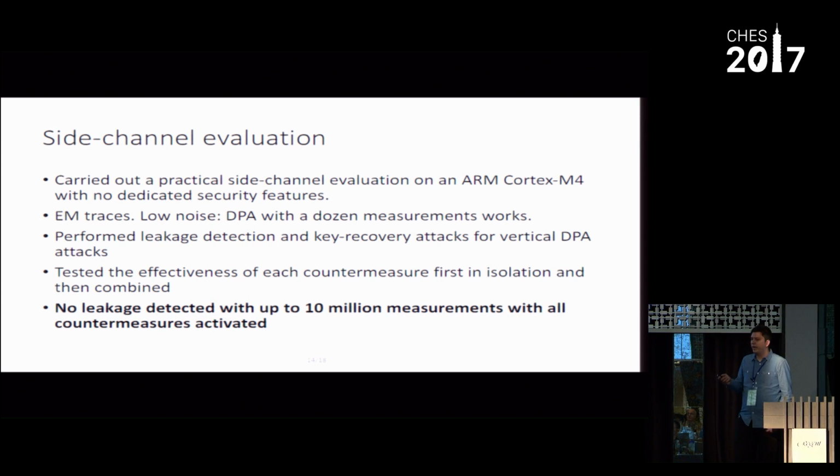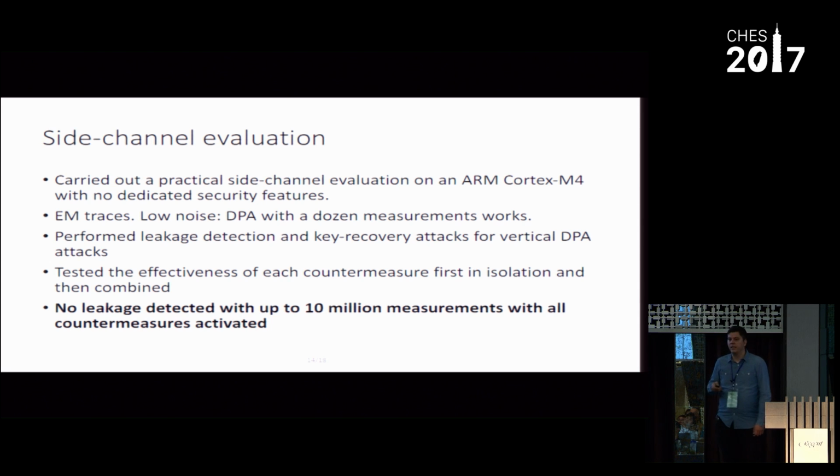So with respect to side channel evaluation, practical experiments, we have evaluated the implementation for ARM M4. This model has low noise, meaning that you can conduct just a few experiments and measurements, have a few traces, and get some nice results recovering the keys if you don't use any countermeasure.